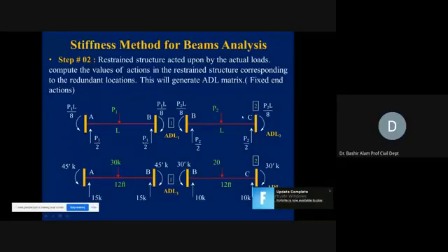Now let's apply this to the general conditions at the bottom. Now we are specific to our problem. 30 was for the AB span. So 30 means you should take out your calculators and verify these values. PL will become 30 multiplied by 12 and divided by 8. I am running my numbers, you should be running your numbers. So 30 multiplied by 12 and divided by 8, and I got 45. And exactly 45 we are showing for these moments, 45 and 45. Vertical reaction, half of this 30, is 15 and 15.